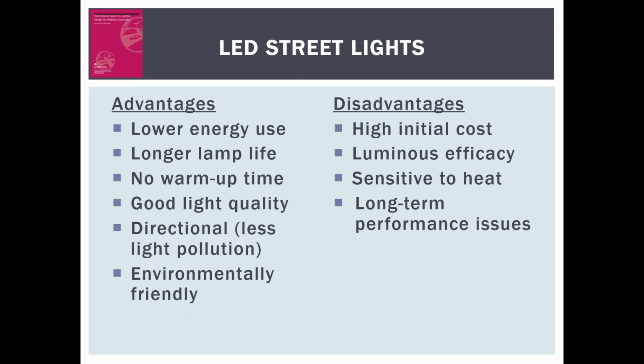And typically the pole costs are higher because for pedestrian level lighting, more likely than not, the desire is to go for an ornamental type pole, which increases the cost. I also asked about the cost for retrofitting existing streetlights into LEDs, and was told about $300 to $500 per fixture for installed cost is a good cost to estimate. And again, this may vary by different parts of the country. There is one caution that based on the fixtures used, it may require more poles to be placed in the roadways in some cases, not in others. So there are some differences on that.